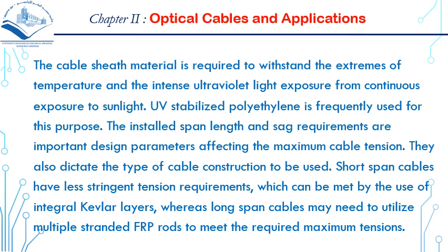Short span cables have less stringent tension requirements, which can be met by the use of integral Kevlar layers, whereas long span cables may need to utilize multiple stranded FRP rods to meet the required maximum tensions.